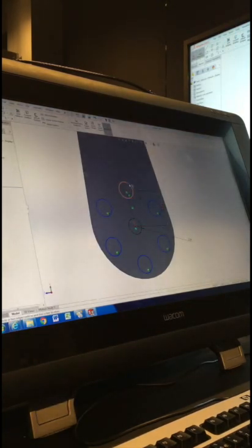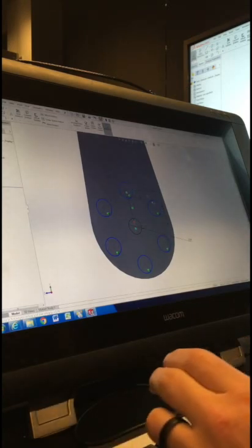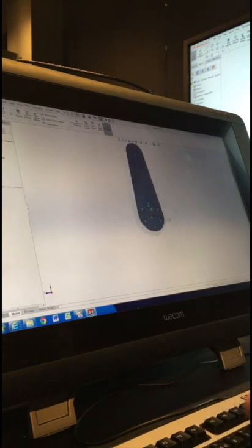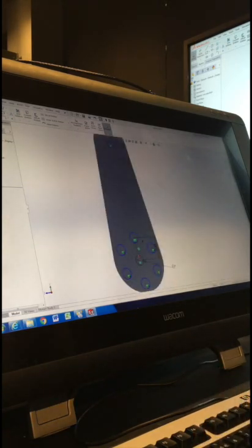The pattern one in particular, because they're already made from a pattern, you only need to dimension one of those holes. But this hole at the top is going to be the same as this one in the middle, down here. Instead of adding a separate dimension at the top, I can select both of those circles, and while I'm at it, I'll select the first circle of the pattern and make them all equal. So they're equal relation. That makes them all equal in diameter.